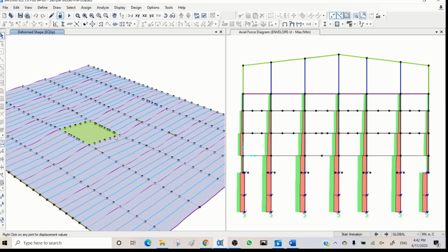You can see that displacement here. For sure that will cause some difference in transferring internal forces here as well. So you should have some numbers which don't sound very logical. Those beams generally should have a regular moment or shear due to gravity load, but we don't have it here. Let's have a look.